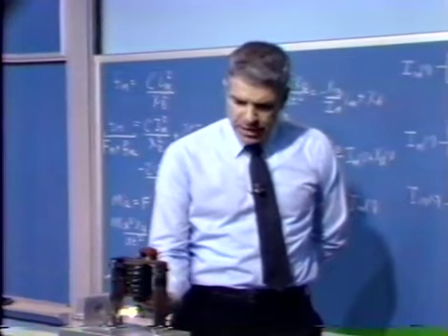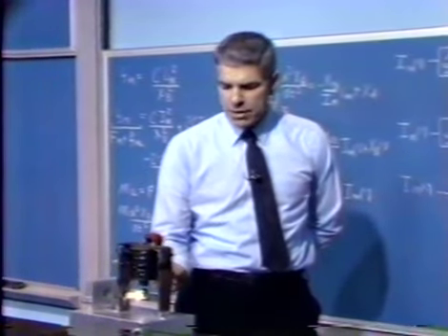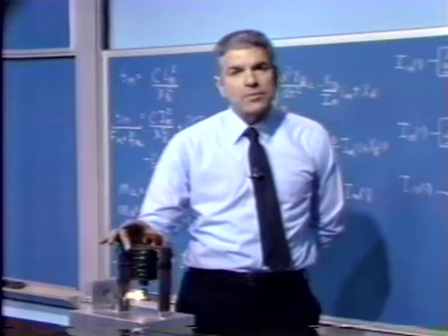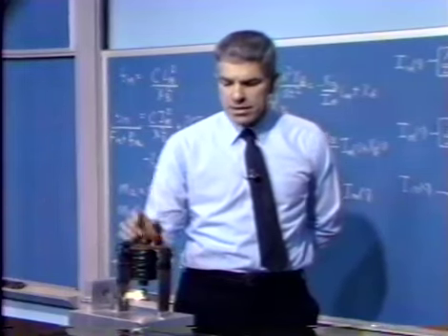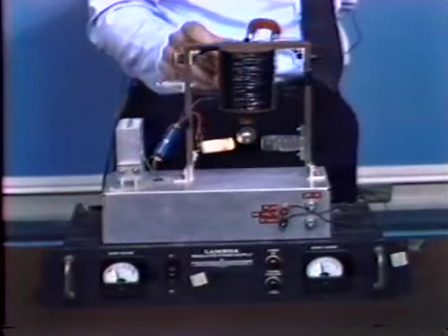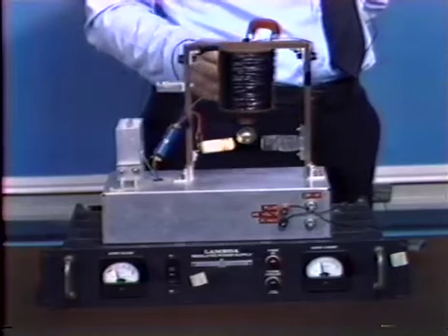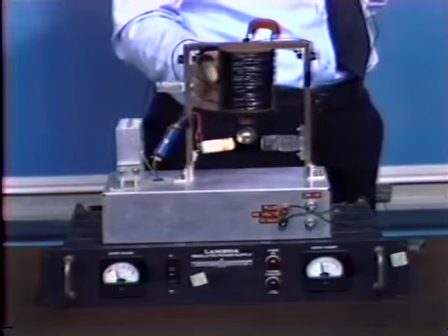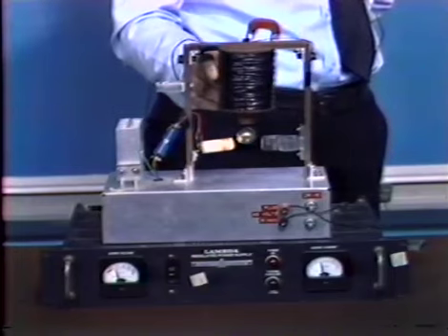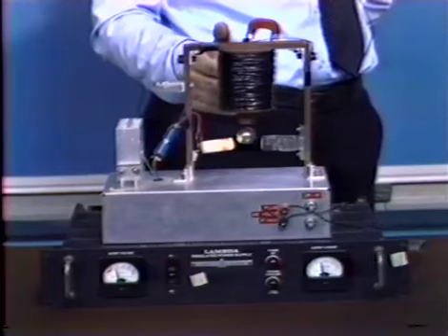but now there's a null position you can adjust or select your operating point to be that where the force associated with the permanent magnet just balances the force of gravity. And when you do that, you still have to worry about the stability of the system. So perturbations you handle with a coil in conjunction with the permanent magnet that allows you to change the total magnetic field.